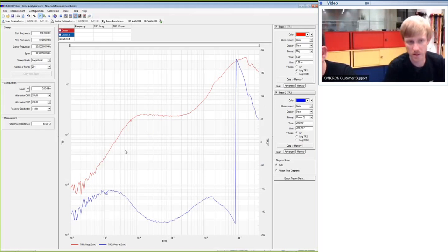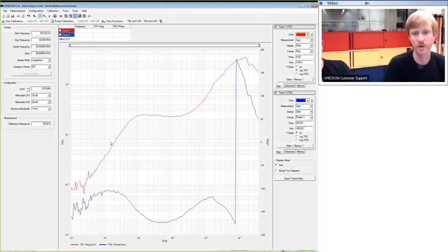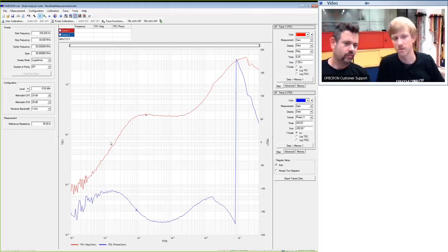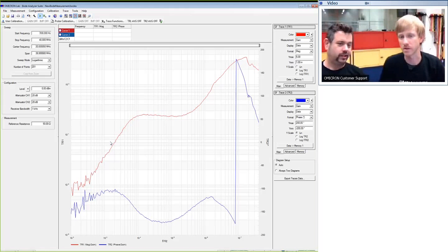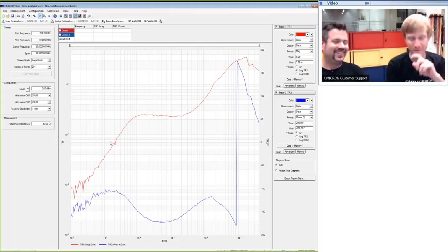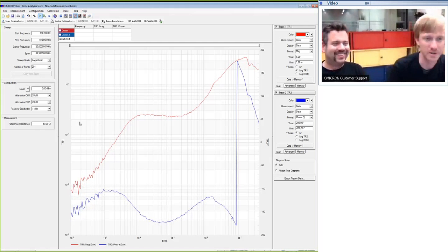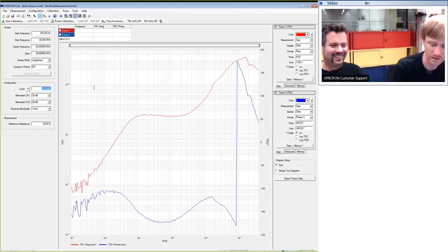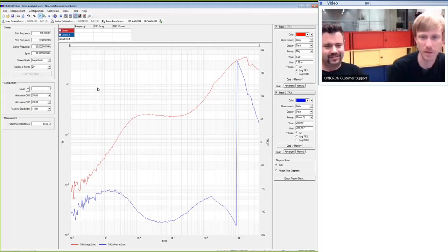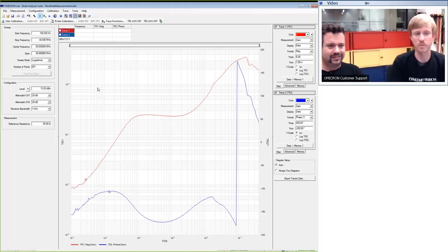Okay, so there is still quite some noise on the curve, and we have many possibilities to get rid of that noise. Bernhard, what would you suggest to reduce the noise in our curve? More power. Okay, not always more power, but in this measurement we can do more power. It doesn't affect the system that much as in the voltage injection, the loop gain measurement. So we now give full power here, 13 dBm, that's the maximum power of the Bode 100 output, and we see that the result already looks a lot cleaner.